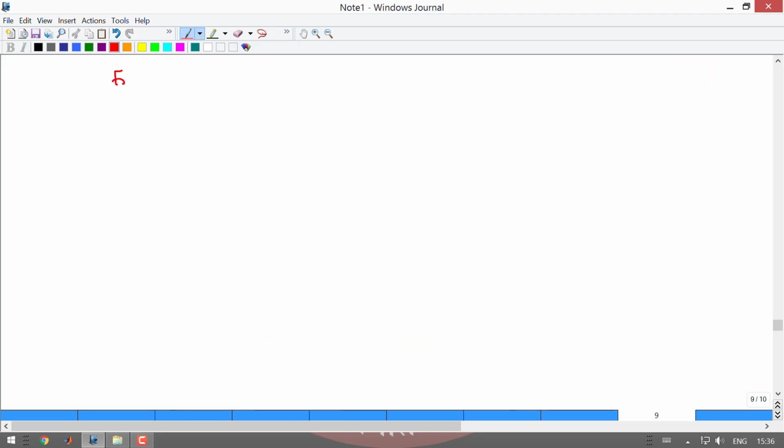So, from the intercept part, 1 by q naught is equal to 3.2 into 10 power 6, equal to mu Rm by A into delta P. Here everything is known, viscosity, I just have to calculate the filter medium resistance Rm.